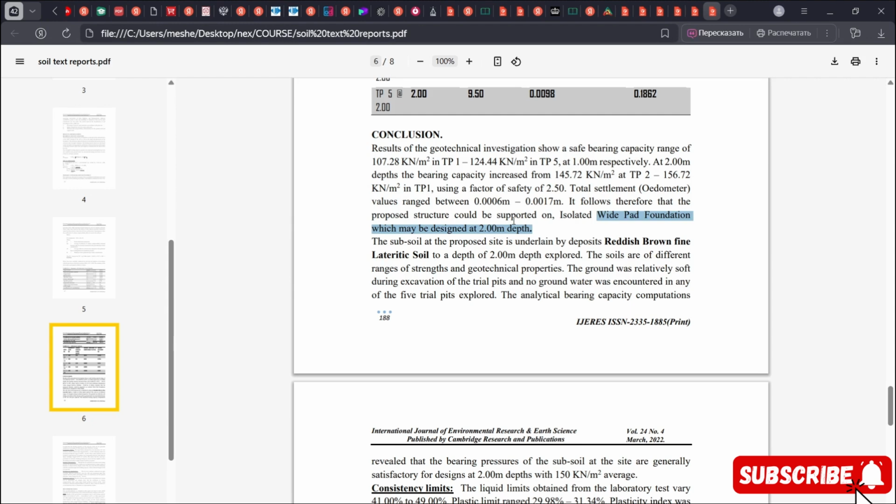If the result is not good, you have to improvise: either increase the thickness of the foundation, or increase the number of reinforcement, or increase the diameter of the reinforcement. Mind you, as a structural engineer, you always have the mindset of economy. You don't have to be going extravagant, just thinking about how the building will stand without thinking about the pocket of that company or client.